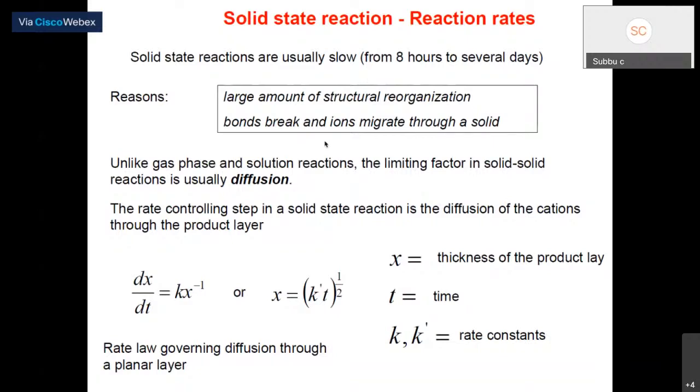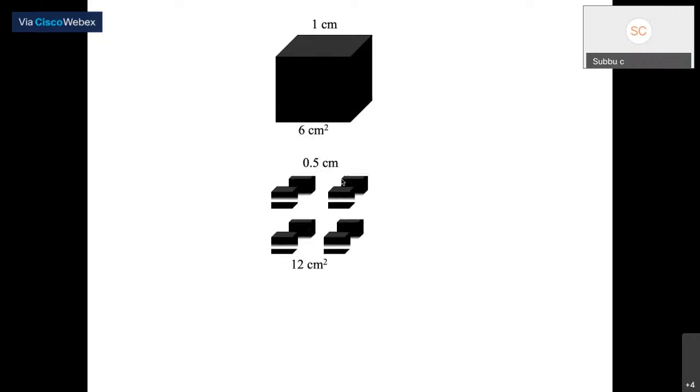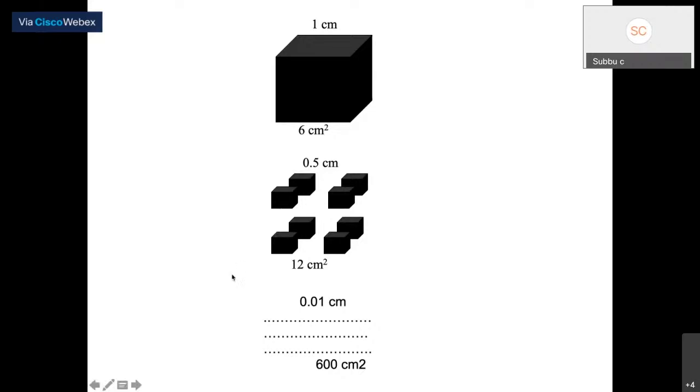Now the question is, for example, sir, I've taken magnesium oxide in one hand and aluminum oxide in the other hand, and I'm trying to mix both of them. How can I mix them? You cannot mix them straight away. What you do is try to minimize the size. You try to grind them first, make them as small as possible. I'm sure that many teachers would have explained, even I myself said it in the first class, that you are increasing the surface.